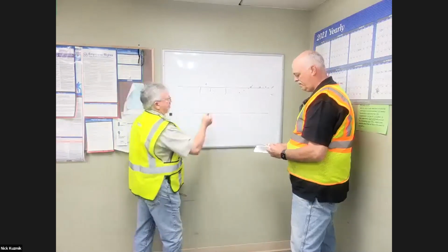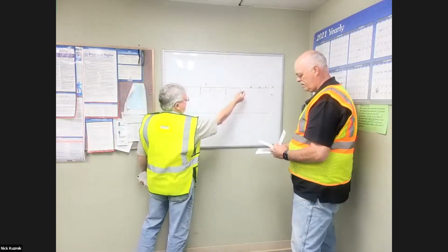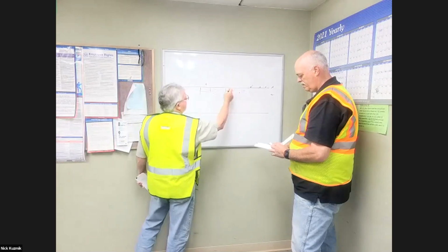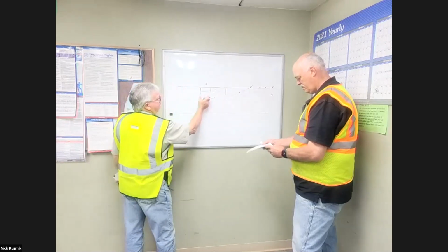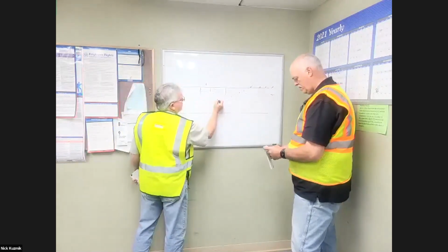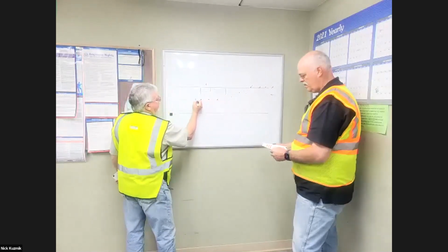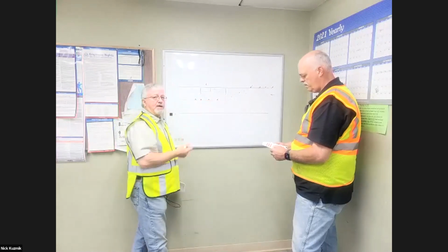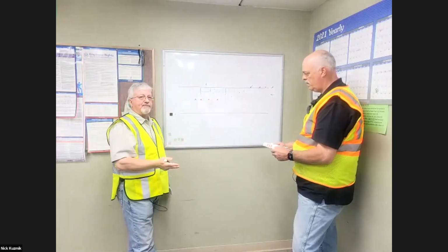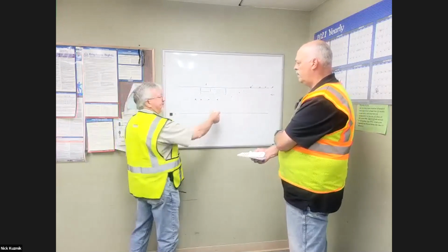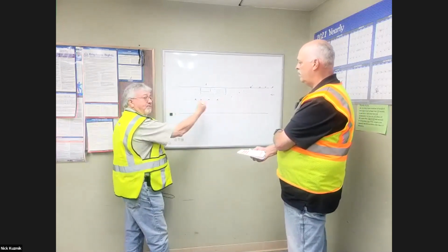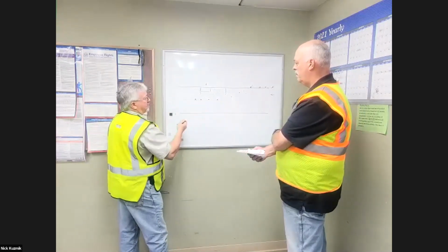So we'll have your taper zone, then you've got your buffer zone, then you've got your work zone, and then your cones will be set up along this work zone here. Their spacing will be set at 2 times the speed of the traffic. So if you've got 35, you'll have them 70 feet apart, and that'll be based on how big your work zone is going to be.